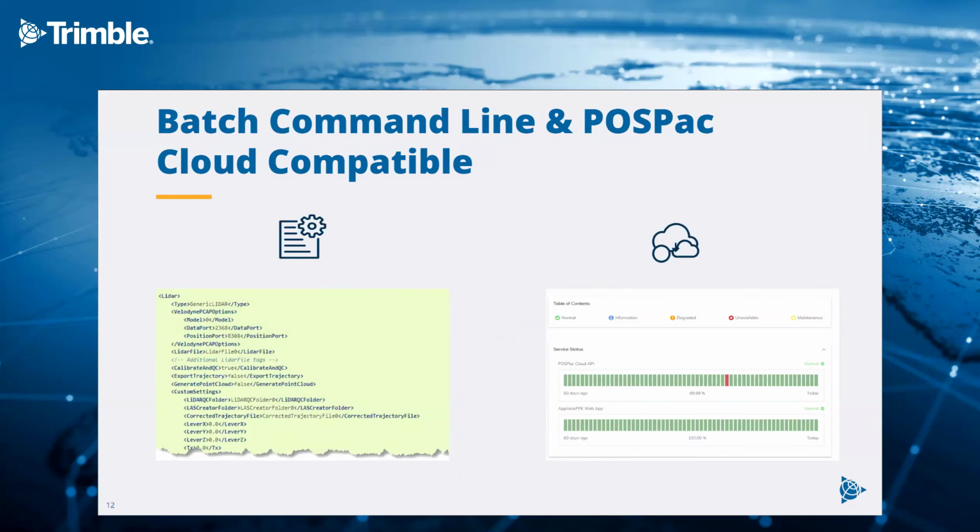So LiDAR QC is also batch command line and POSPAC cloud compatible. So the batch command line executable triggers automated processing without running POSPAC in the graphical user interface. That means users can define a batch template, which is an XML file, to be used in a production environment where basically only the input parameters or the raw data really change between the different missions, which is the rover data and, if you have it, the base station data.